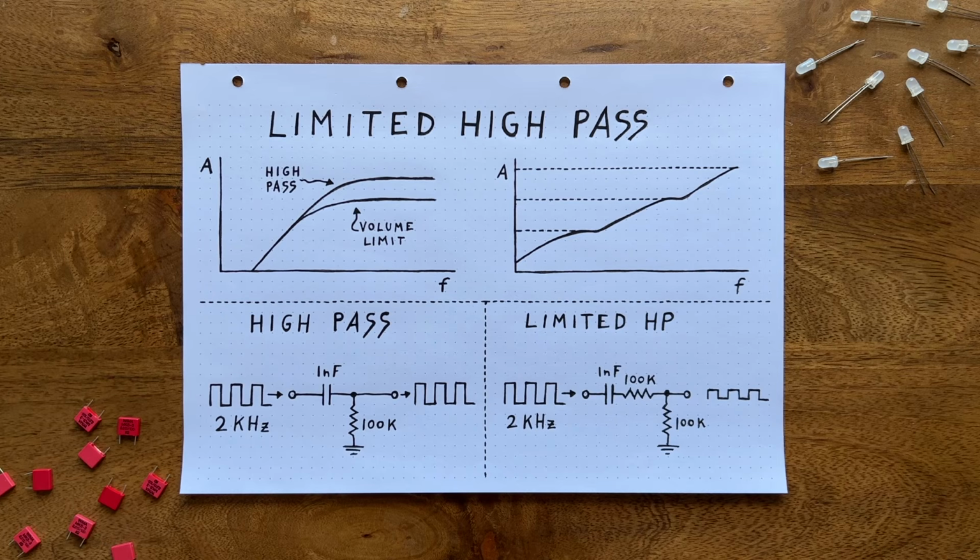You'll notice that the only difference here is this additional resistor after the input capacitor. To understand the effect this has, let's recap the mechanics of a high-pass filter. As the name already implies, a high pass is the exact inverse of a low pass, functionally, but also on the component level. So where the low pass had an input resistor, the high pass has an input capacitor. And the capacitor to ground gets swapped for a resistor to ground. Easy. If you now again think of the capacitor as a charge-dependent resistor, it should become clear why high-frequency oscillations are allowed to pass through, but low frequencies are blocked.